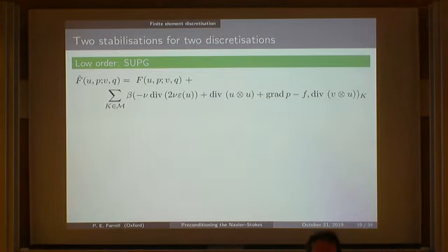Okay, one last aspect of the discretization before I move on. For the low order scheme, it's really crucial that you stabilize, because it's oscillatory at high Reynolds numbers. And so a popular stabilization scheme is the streamline upwind Petrov-Galerkin. I won't talk about it too much, except to say that if you try this with the Scott-Vogelius element, it's a disaster.